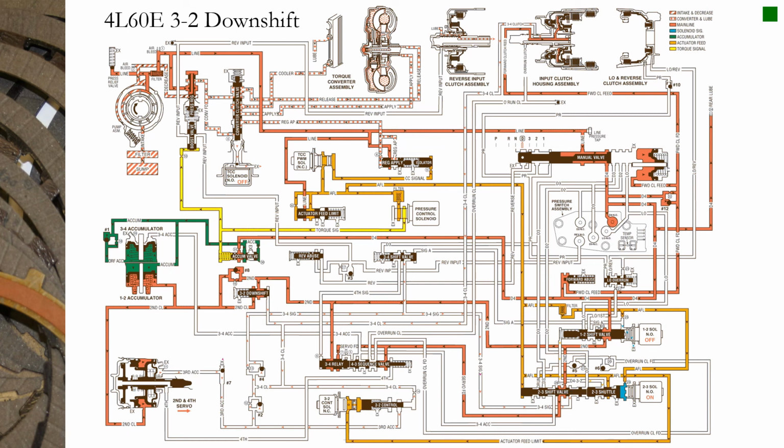But when you're downshifting, there are really a couple of states of downshift. If I'm just coasting to a downshift, like the traffic light turned red and I've got my foot off, I'm just coasting down, I'm going to downshift 4, 3, 2, and 1.